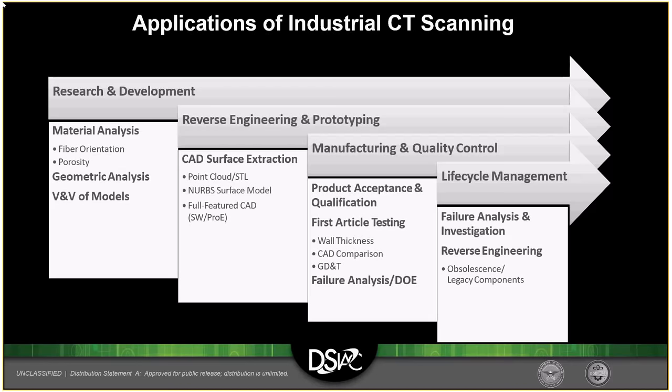model, CT scanning is very favorable because in that stage of your research and development, you don't have a lot of samples, so when you have to destructively cut something open that you plan to test, you ruin that sample, or you have to make another one, and that can be a time factor and also a cost factor. So with CT scanning, you can peer into things and look inside and still use that part for further testing.